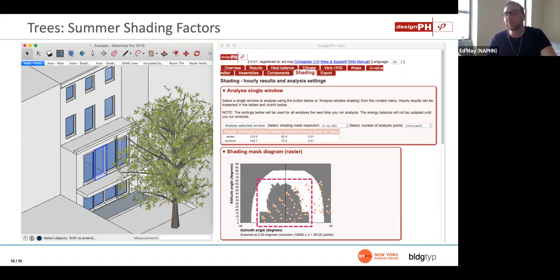Now, the easier tool that we use to get building heights is actual GIS data, and you can get that automatically through something like OpenStreetMap. If you use openstreetmap.org, you can navigate to your location and download an OSM file. That OSM file is going to have all the municipal GIS data that's publicly available. And it's almost always going to include building heights.